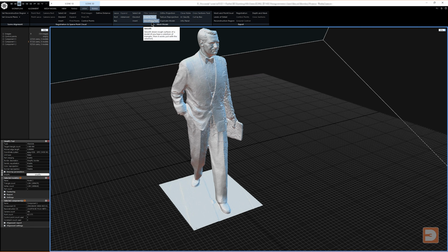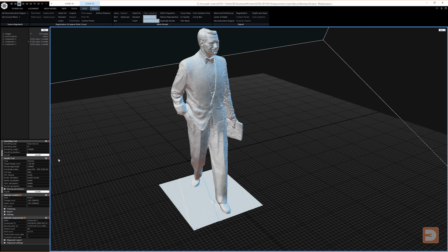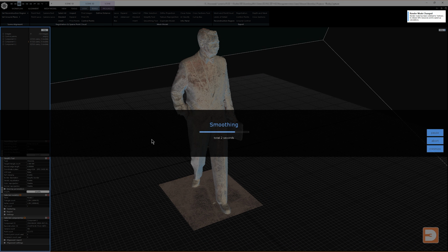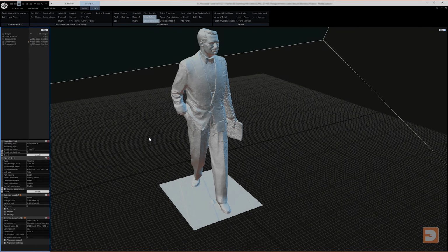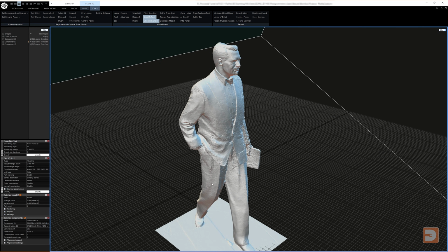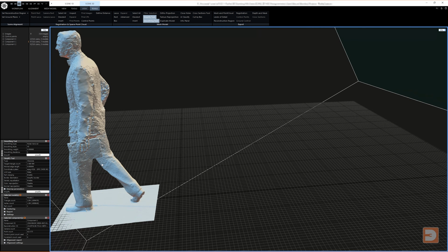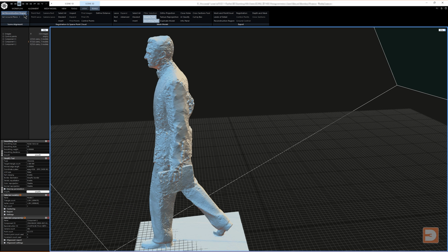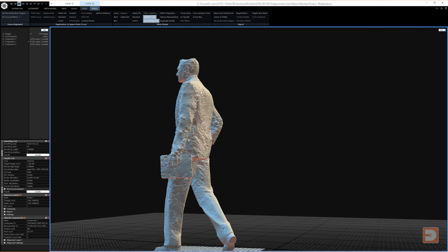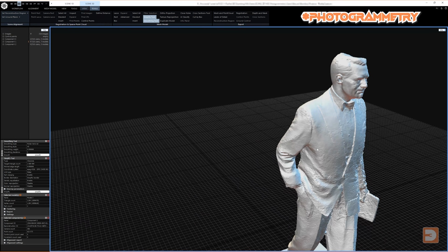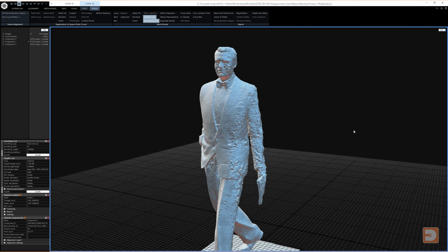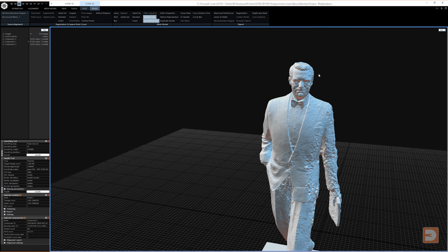Some software like Reality Capture also has nice features like smoothing and model cleaning that'll try to remove any defects from the model and smooth out any bumps and errors. You'll notice that this side of the statue is far less detailed and features more errors than the other. This is the side that was in shade and so is much darker in photos due to the hard sunlight. This highlights the advantage of outdoor photography on overcast days, as opposed to sunny days like when I did this. More even lighting across the model means better results.